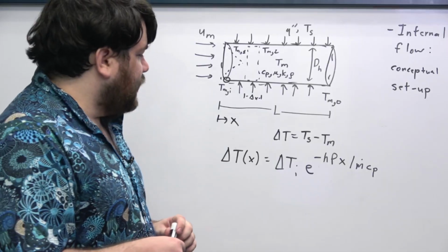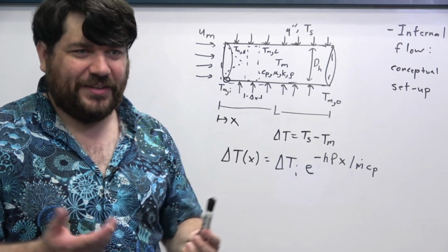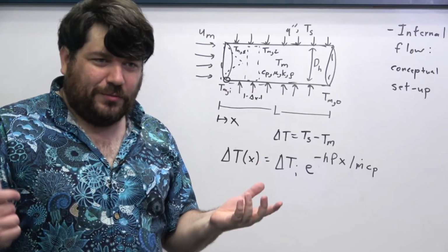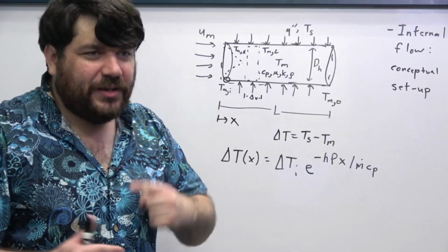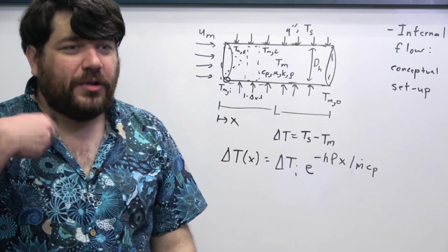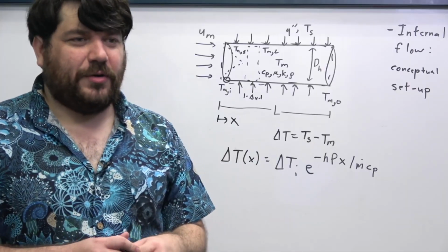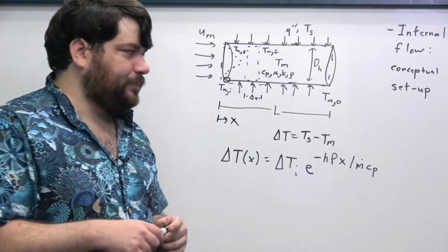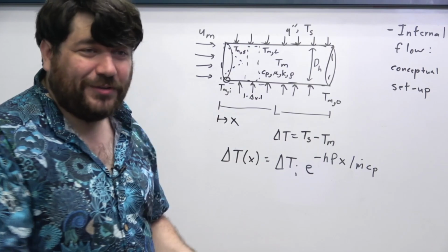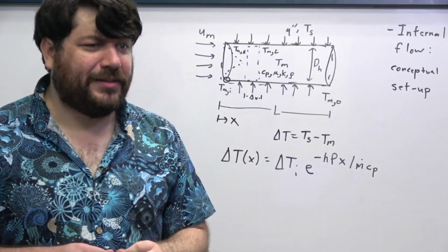And you can imagine that using either this equation or the differential equation that we saw before, where we just say that dTm/dx is a constant, combined with that golden rule, those equations, for each different kind of version of the system, will allow us to determine things connected to internal flows, like heat transfer coefficients and heat transfer rates, as a function of everything else in the system. Or even that we can use those heat transfer rates to find outlet or inlet temperatures.